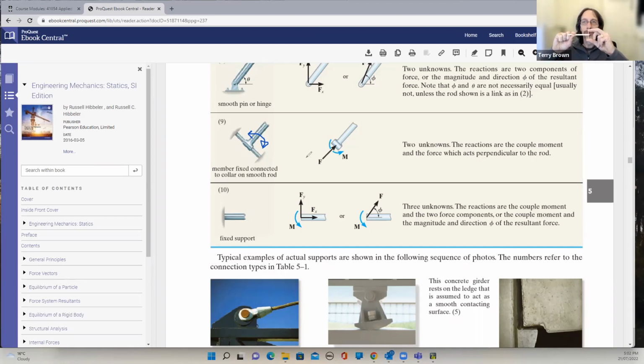So here we've got an object. Let me turn it around so it looks the same as what's in the textbook. So here's my object. It's free to move up and down. I've just got some holes in the paddle pop stick and this stick in my right hand goes through those two holes. So it's free to move up and down, so no reaction force tangent or parallel to the smooth rod. I can't pull it perpendicular to the smooth rod, so we've got a reaction force there.